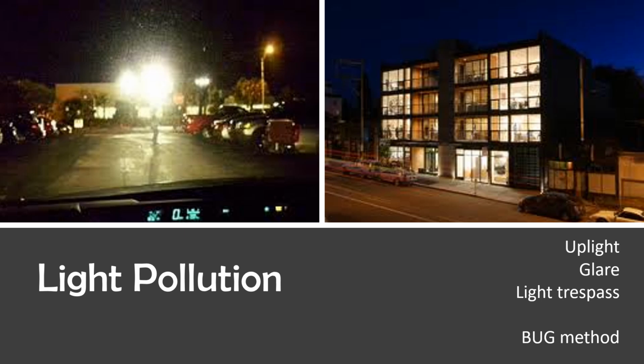To get the credit, you need to meet the uplight, glare, and light trespass requirements using either the BUG method, backlight, uplight, glare, or the calculation method.